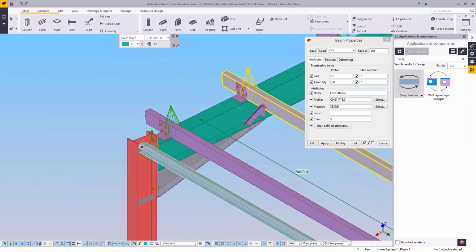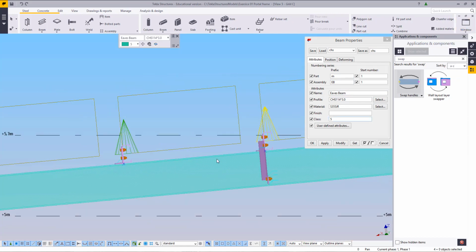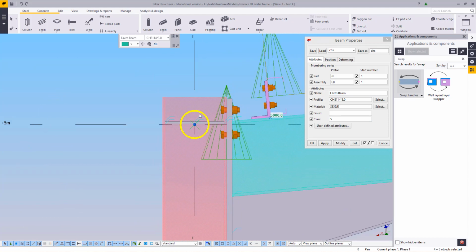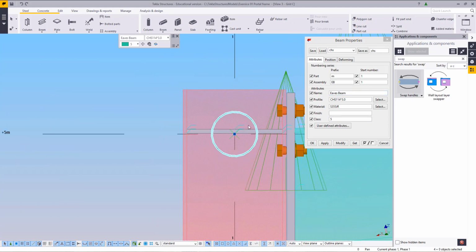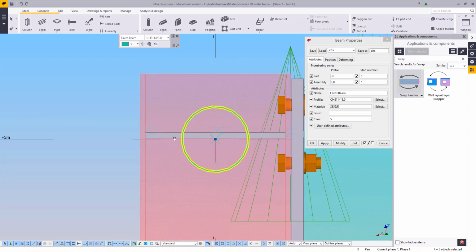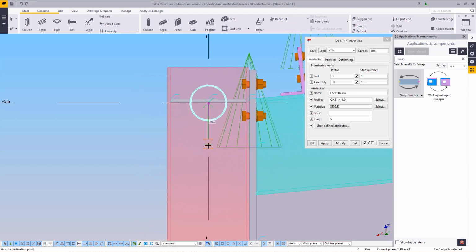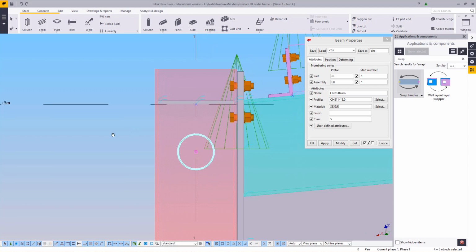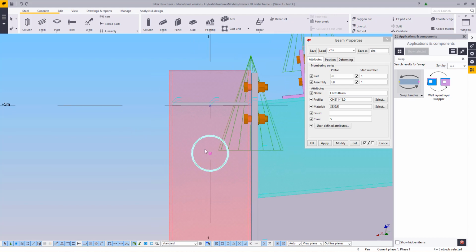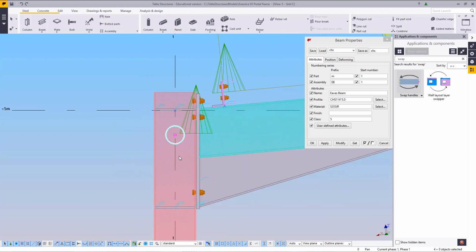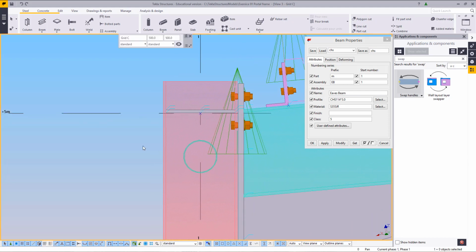As I said previously, this is the mark and this is the name, so try not to swap them around. If we go down here at the bottom, you'll find that they are clashing, and this is not a problem. With an ES beam, the position is fairly unimportant, you could say. So we can move them down 100, 150, however they need to still be in the haunch area of connection, but not interfering with the connection. And that should be good.